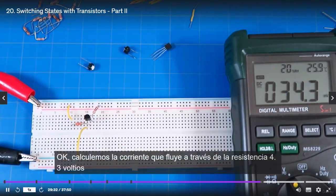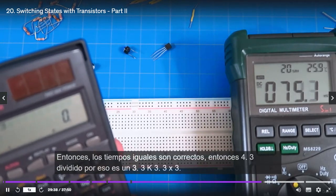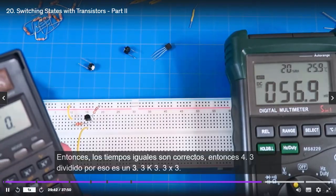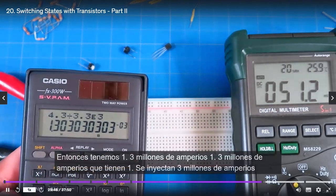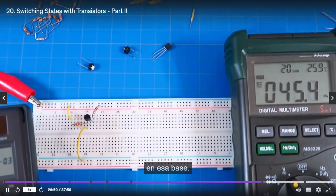Okay, let's compute the current flowing through the resistor. 4.3 volts, so V equals I times R, right? So 4.3 divided by, that is a 3.3K, 3.3 x 10^3. So we've got 1.3 milliamps. So we've got 1.3 milliamps getting injected into that base.